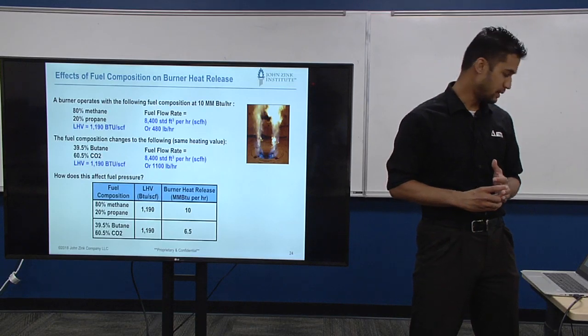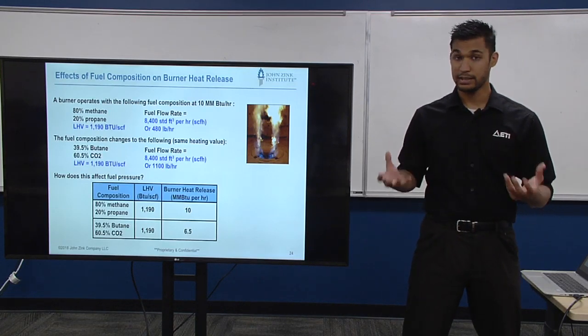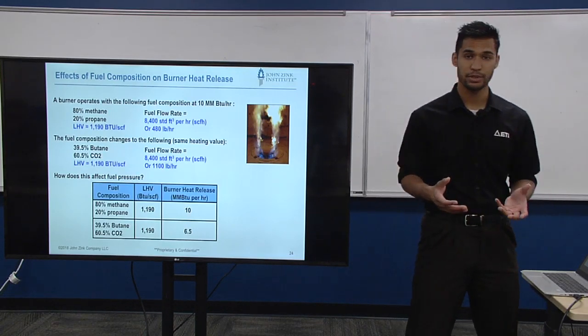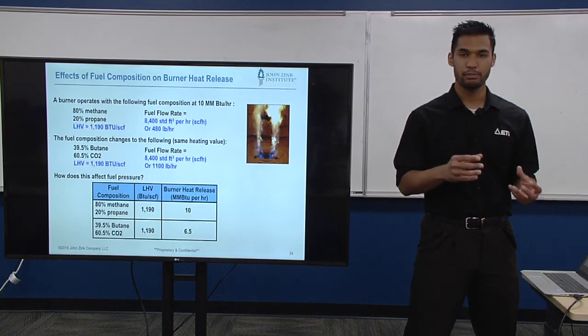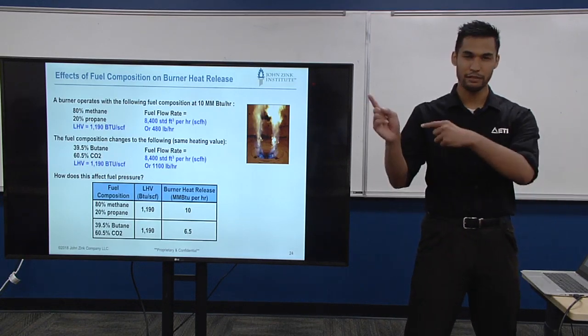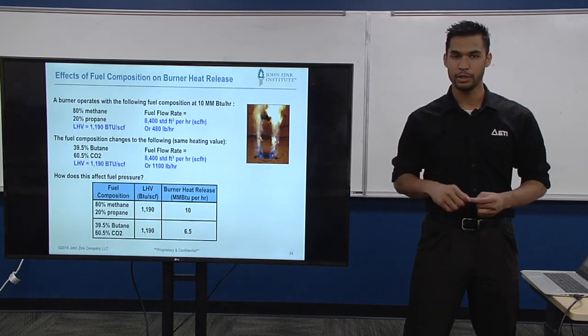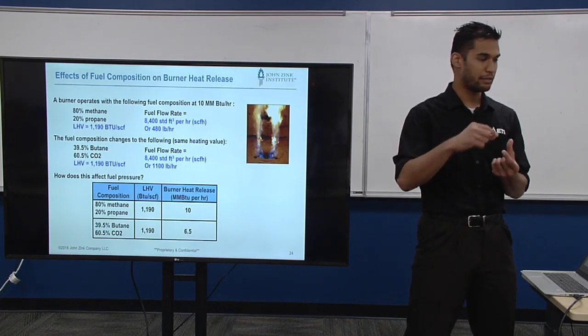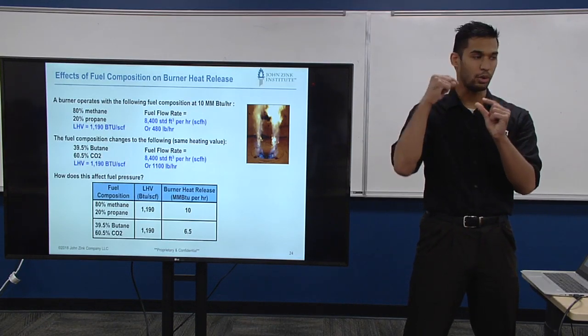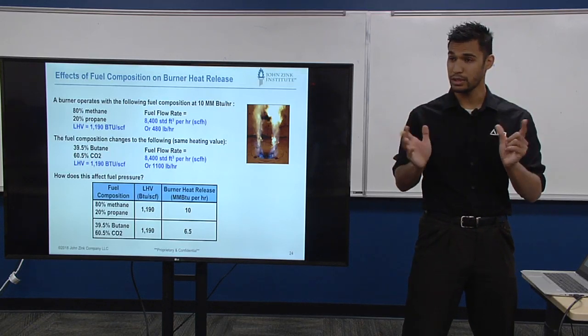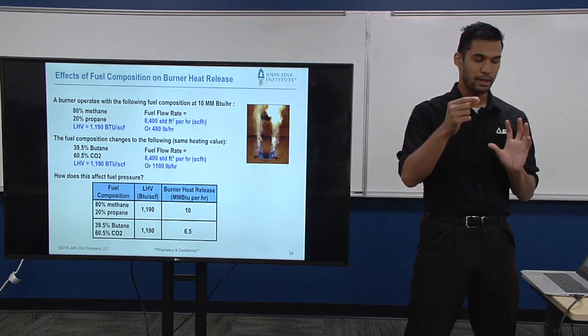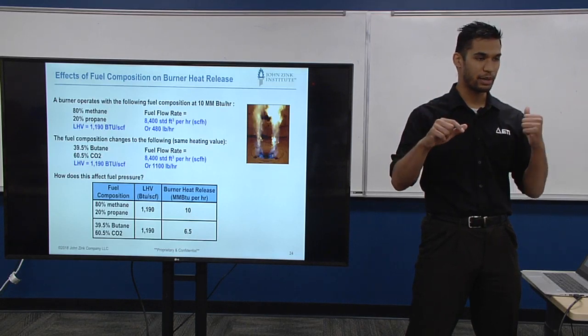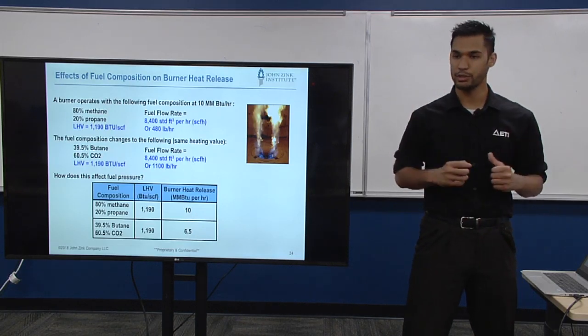Not only can this affect the stability of the burner, but you also have different delivery pressures required to push that fuel out of the tip of the burner. Okay? Because usually you'll have a fuel tip and there'll be a hole in there, right? Or several holes. And the fuel flow rate is determined by the pressure behind it and the size of those holes.